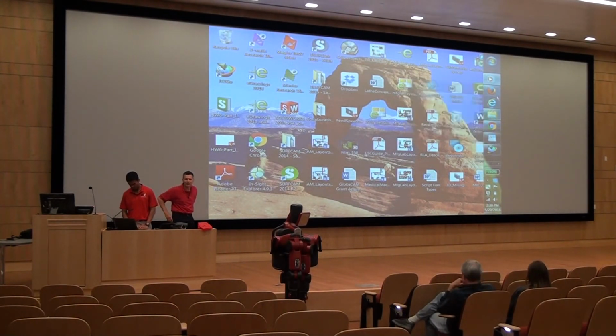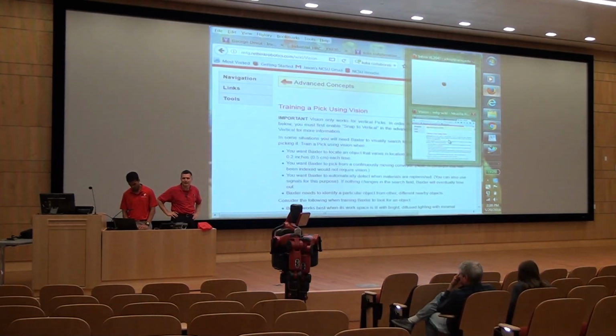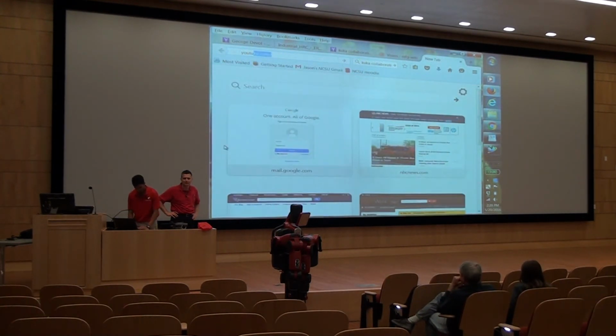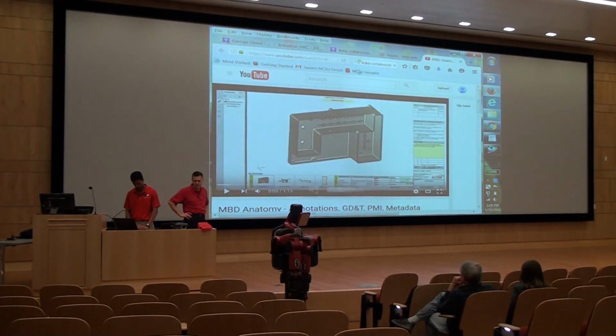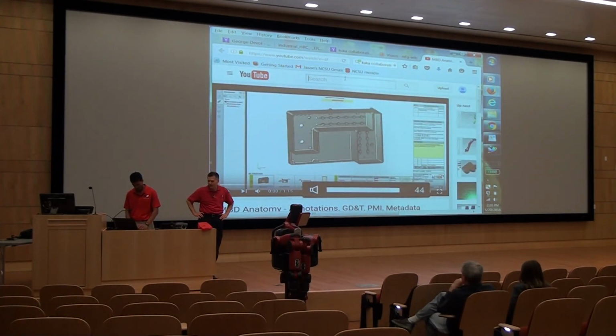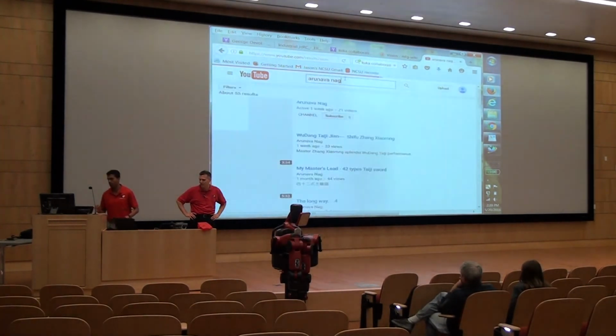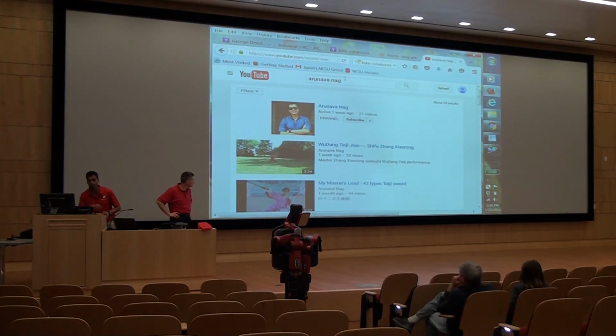The 3D space modeling: can you describe the representation model for 3D space in your software and how you interact with it? Is it vector? Is it Cartesian? It's Cartesian XYZ data. So basically, when we get the data from the camera, that is 6 degrees of Cartesian coordinates. When you feed it to the inverse kinematics or the IK solver, it goes into 7 degrees of robot joint angles.